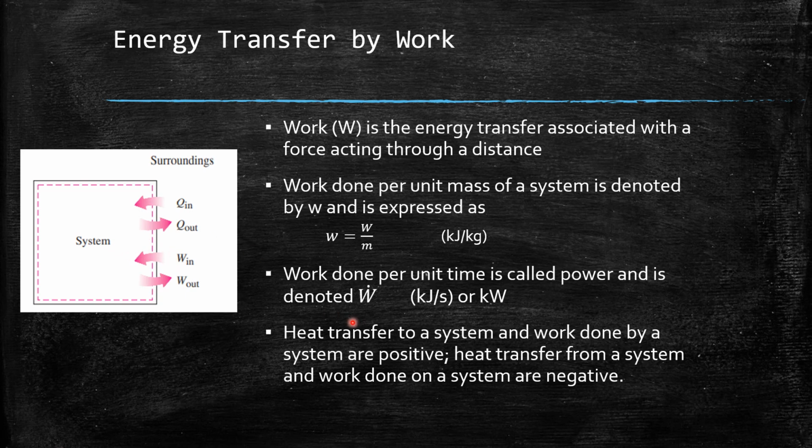And if there is heat transfer from a system, meaning it goes out, and work done on a system, it has a sign of negative. Another way is to use the subscripts in and out to indicate direction. So in is positive, out is negative.